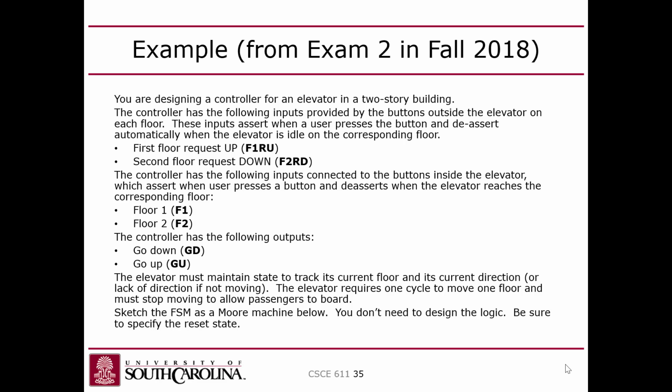If there's an unconditional transition, is that truly a state then? Yeah, because the idea is that we want to spend a cycle in this state. The reason we have this state with the unconditional transition is because it says in here that it requires one cycle to move one floor, right? So we want to pass through this state to give it that travel time. But then it's unconditional because it only takes one. Now, if it took like 10 cycles, then we'd have 10 states. It would go through 10 states. But it takes one state to move. And then we get to the second floor, idle.